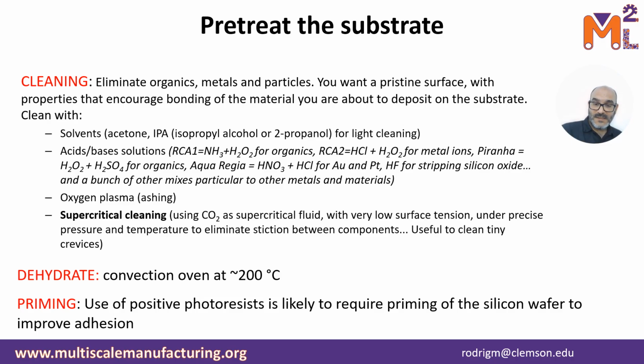Now, going back to the previous slide, basically it was mentioning the choice of the substrate. So basically mentioning that you had to consider the differences in the coefficient of thermal expansion between your substrate and the SU8 or the photoresist that you're actually trying to pattern.